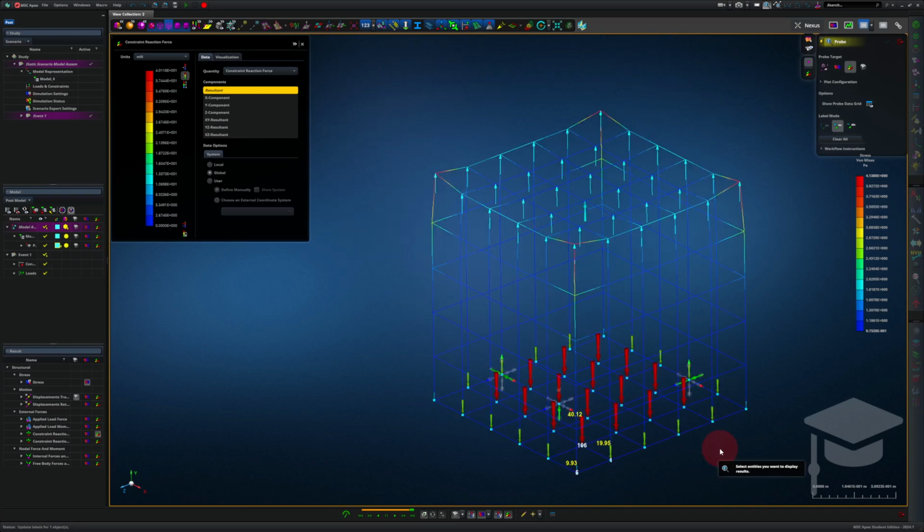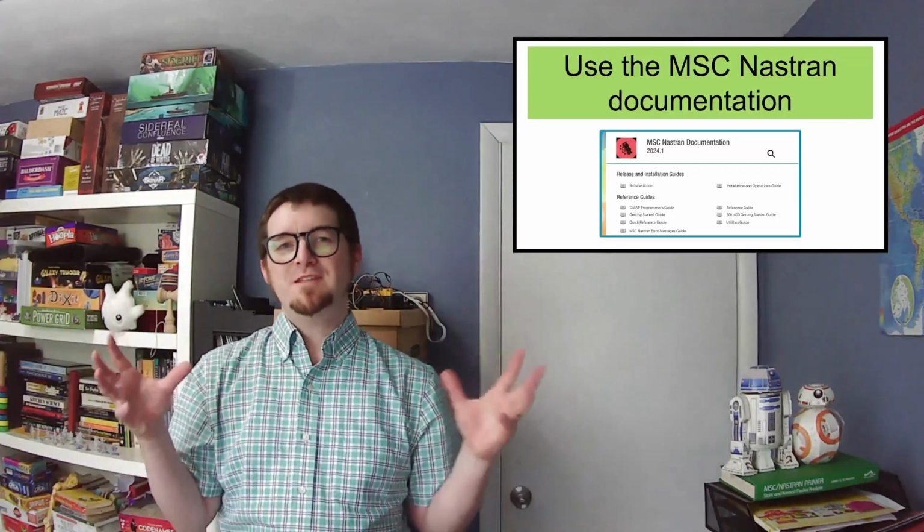Now the stresses looked pretty uniform at the bottom of the block, and for us to get that, we needed non-uniform reaction forces. So maybe we need forces to be applied at the top in some other way other than perfectly equally. And that actually having equal forces all across the top gives us unequal stresses. Well, surely somebody's had this problem before. That tells me that it's time to go look at the documentation and see, are there other options? Are there best practices that we could use? That brings me to my first tip.